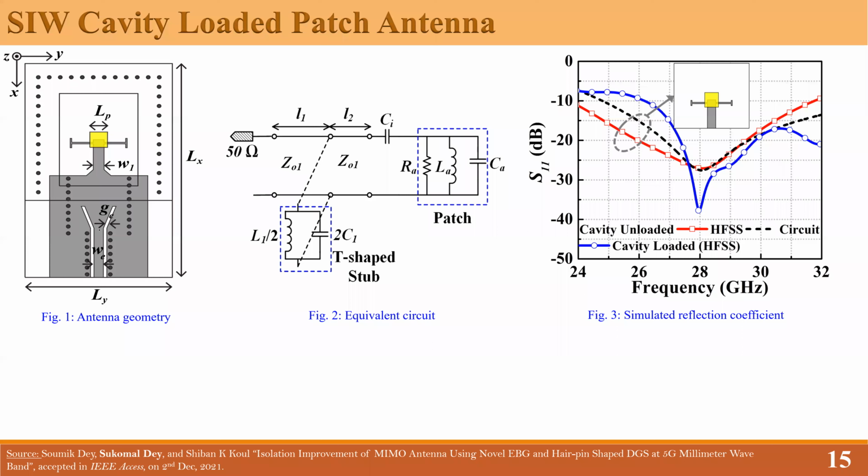Here we are basically giving some kind of signal feeding, and the signal feeding will be based on a microstrip line. Then it will convert to waveguide modes. You know that a microstrip line basically gives you a transverse electromagnetic mode, TEM mode. When it reaches the waveguiding structure, it has to support the TE10 mode. So that kind of mode transition should be there in your structure.